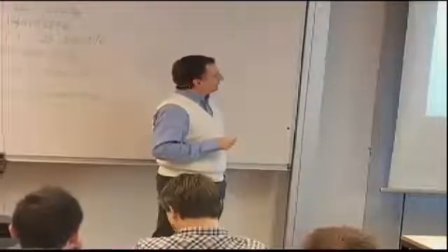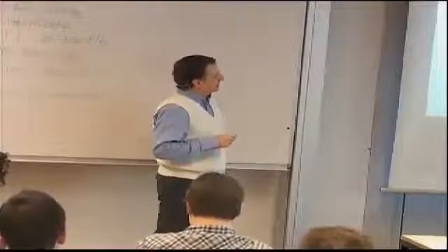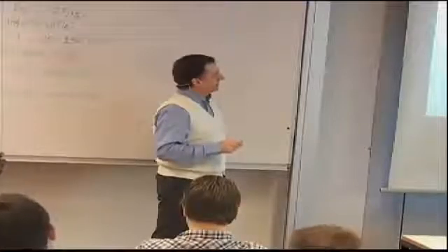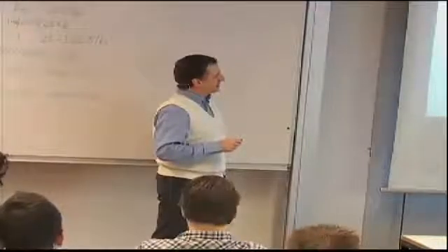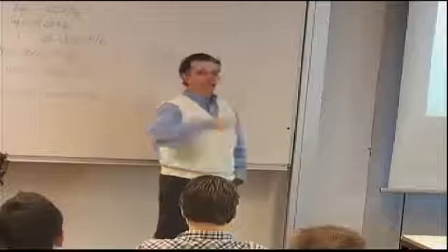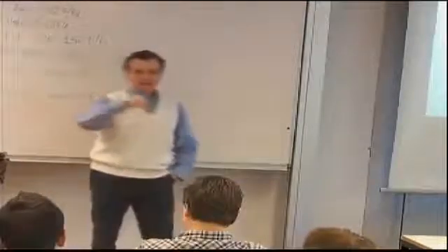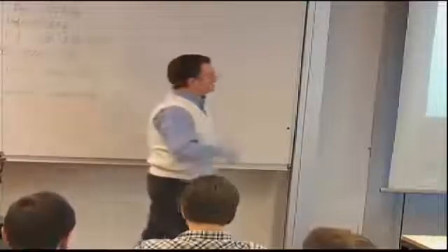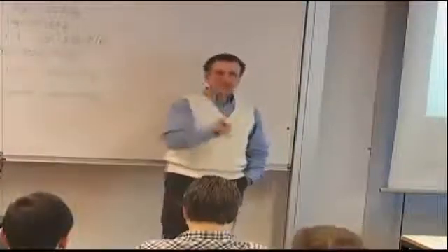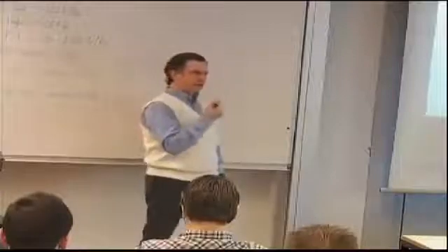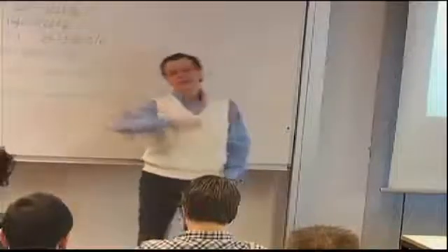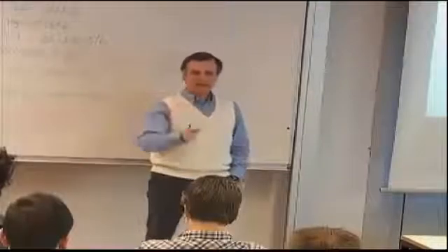So if I can detect, we define this parameter, threshold of detectability, and that means that whatever method you chose, it may be able to detect a certain type of damage of a certain size, and if it's smaller than that, it's not reliable enough to detect it. So if you are right at that threshold of detectability, you have to design your structure to take ultimate load, because you have to assume that your structure at some point during its life will actually have that damage in it.